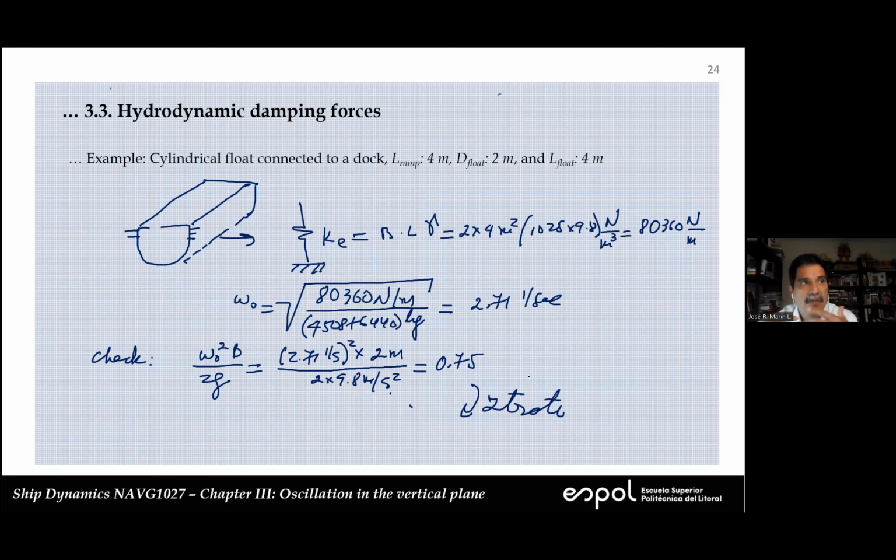If you put some forces, some waves which are exciting the ship, how are you going to identify the values of the natural frequencies? Anybody? No? With the resonances, you can see there is an increment in response at certain regions, and those resonances correspond to natural frequencies.